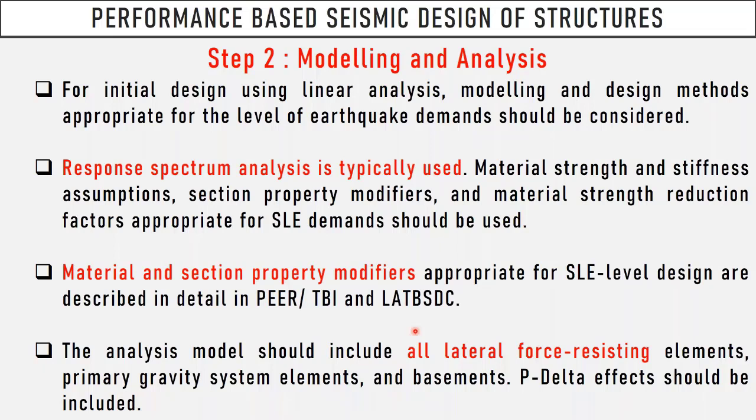Typically, what is used is a response spectrum analysis. Your material strength assumption may change from approach to approach. Which are you going to use, design strengths or expected strengths or characteristic strengths? In terms of section modifiers, are you going to use cracked section stiffness?